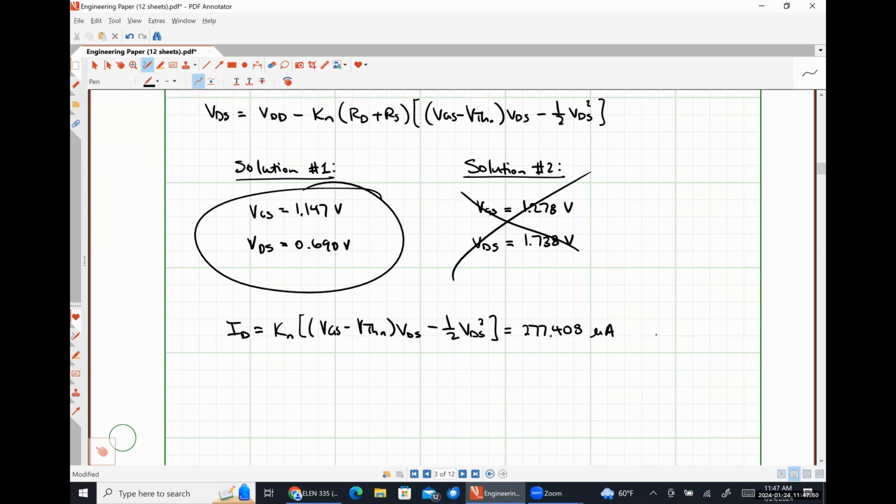So the supply voltage in a BJT is VCC because it's the voltage applied at the collector terminal, the highest point of potential. In a MOSFET, it's typically VDD because we apply the highest potential at the drain side. That's literally it. So VCC for BJTs, because in an NPN BJT the collector is at the point of highest potential. VDD for NMOS because the drain is at the point of highest potential. I don't know why they came up with that, but that's all it is.